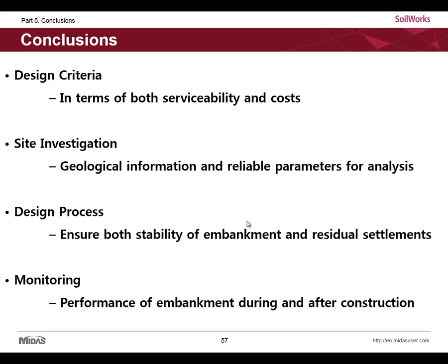Secondly, we should know well about geological and geotechnical information through site investigation and lab tests. This will directly affect the analysis results and design parameters. Third, the design process. This is also related to cost effectiveness, how much time it is going to take to get applicable, thorough design parameters, which can ensure both stability and deformation.